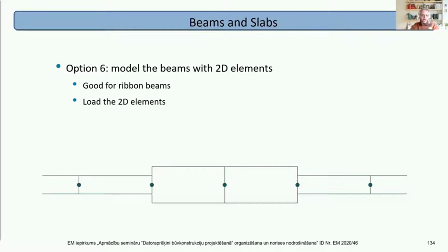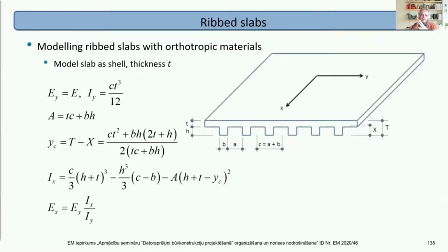Okay, so overall modeling. Now, another option we can do with concrete slabs is modeling explicit ribs. Now, here's another option. It's a rib slab, but we use implicit ribs. We don't directly model them. So we model flat shell elements, and we model the shell.